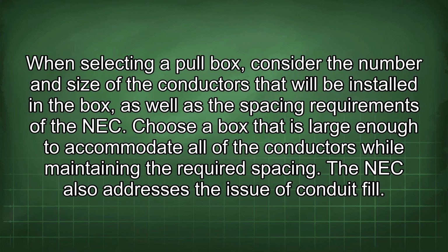When selecting a pull box, consider the number and size of the conductors that will be installed in the box, as well as the spacing requirements of the NEC. Choose a box that is large enough to accommodate all of the conductors while maintaining the required spacing.